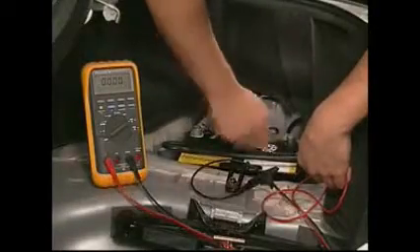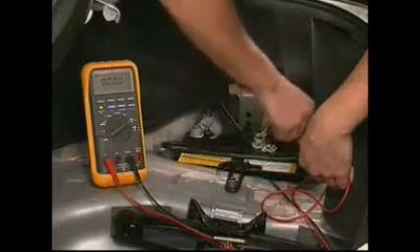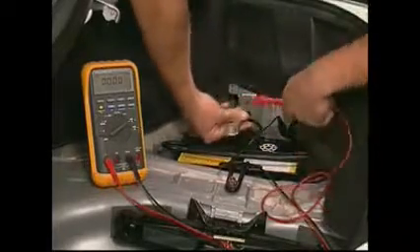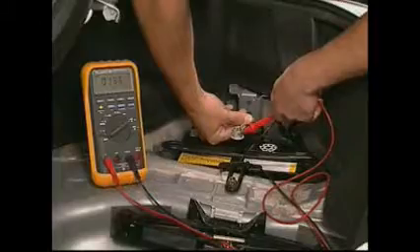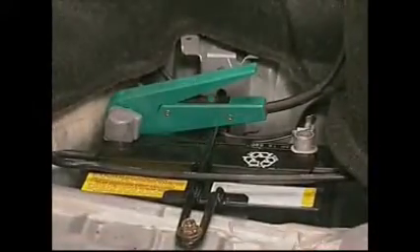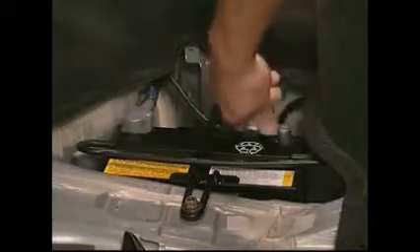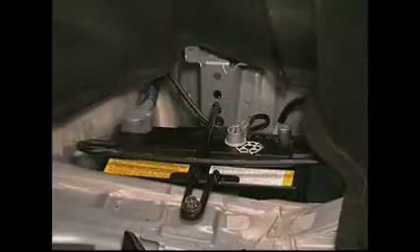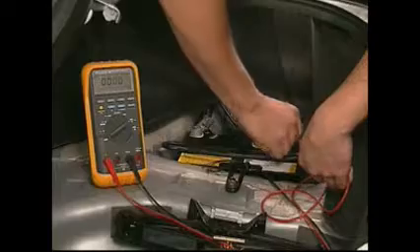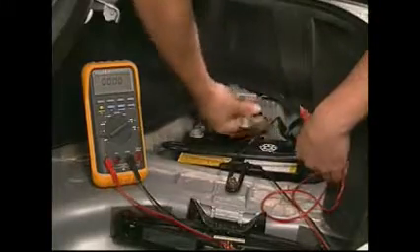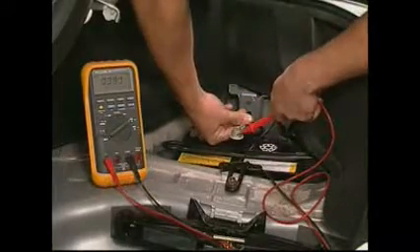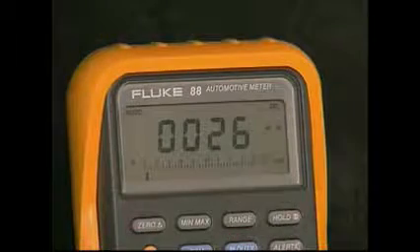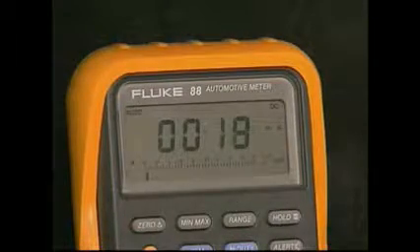To test for current flow, the ammeter must be used in series with the circuit so that the current flows through the meter. If the meter has an inductive current clamp, you do not need to open the circuit for testing. If the meter does not have an inductive current clamp, disconnect the circuit from the battery or remove the fuse. Then touch the red probe to the side of the break closest to the power source and touch the black probe to the side nearest the ground. The current flow through that portion of the circuit will be displayed on the meter.